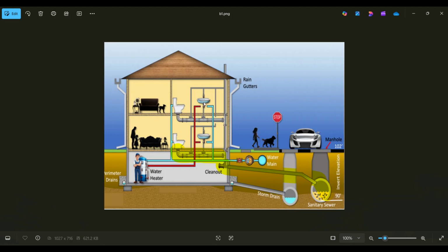So we have three sort of pipes: we have a drain pipe from this closet, a wastewater pipe from this toilet, and then we have a vent pipe in order to remove all the harmful gases, etc. And then all the effluents from these particular water closets get transmitted into our sanitary system. We have a clean out here in case there may be some blockage, and then these get transmitted into our sanitary sewer system, which is provided by our locality.